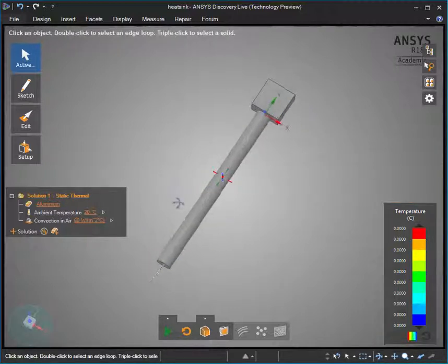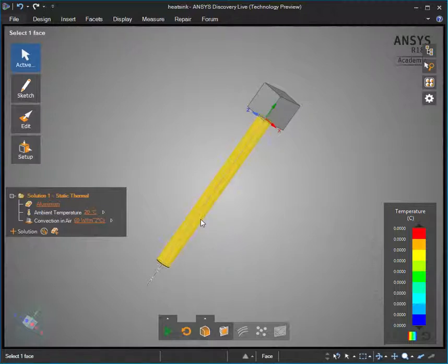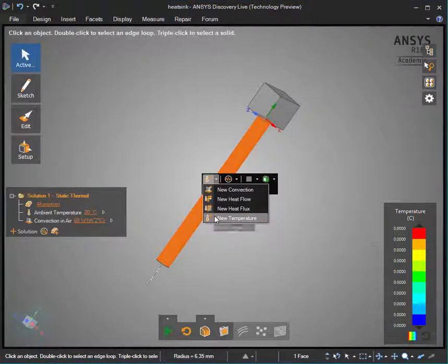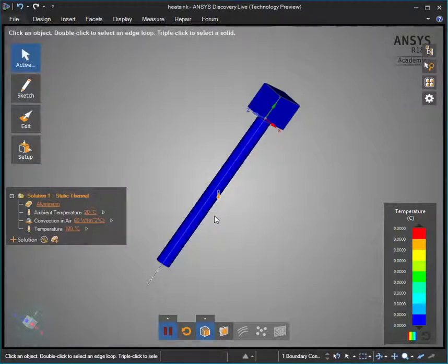We do need to define basic boundary conditions here for it to be able to show us anything useful. In particular, we have to tell it either a heat flow or temperature of one of the objects. So I'll select the cylinder here and set it to a temperature of 100 degrees Celsius. In our trial tests, that will be in boiling water, so that's pretty close. The whole rod may not be submerged in the water, but this will give us a good approximation.